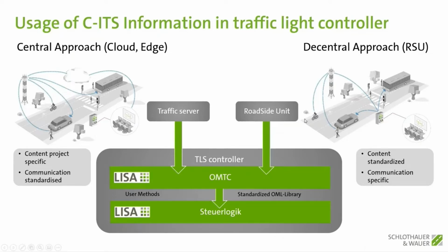This is the roadside approach, and the central approach, the cloud based one, means that you use cellular networks to exchange information, meaning that you need a base station where all the information is collected. You need some servers, maybe it's an edge solution or a cloud solution, and then you need some wire back to the controller just to make sure that the information is available for the signal control.